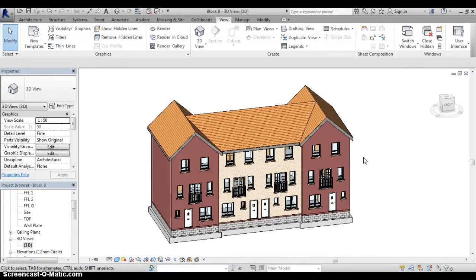For those of you that use a laptop and perhaps don't regularly use a mouse, there's one other tool that I will draw your attention to, and in order to access it you can press F8 on the keyboard, or you can hold down Shift and press W on the keyboard. So it's either F8 or Shift and W, and this brings up a tool that's known as the steering wheel.